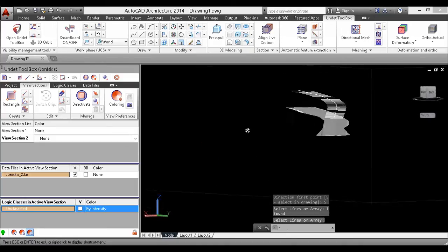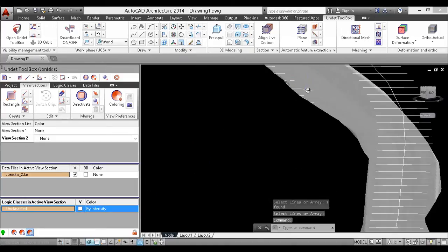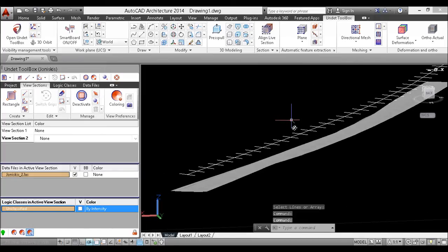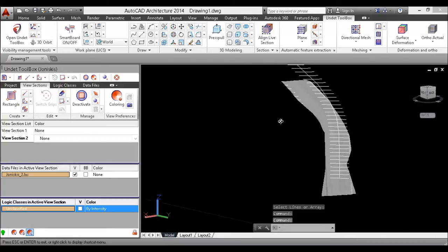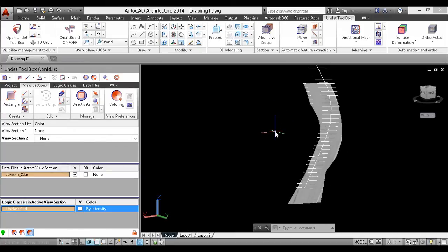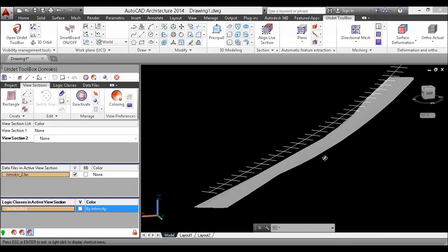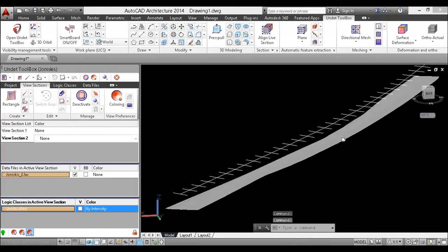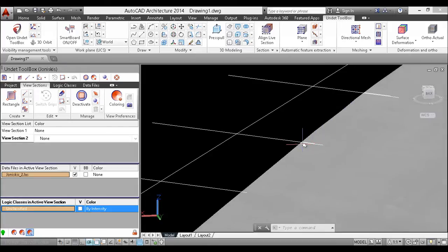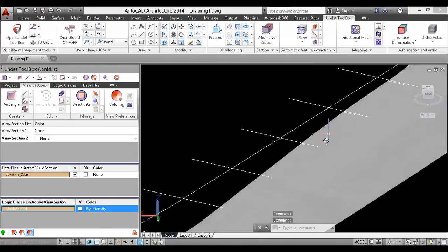Right, so my... yep, and this was my mistake, and I'll probably leave this mistake on purpose. So these multiple mesh sections were generated incorrectly because it directly depends on the view. My view was something like this when I was generating these sections, and those lines that passed by the mesh generated small sections over here, as you see.